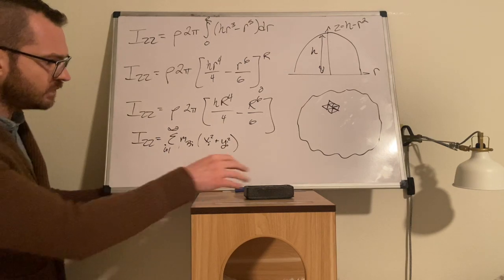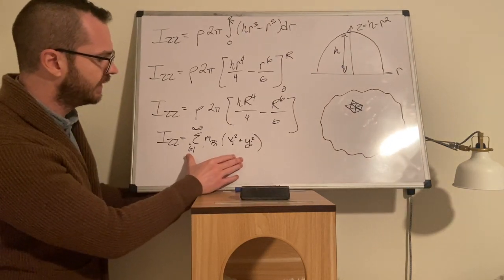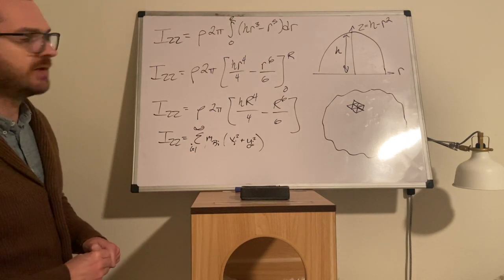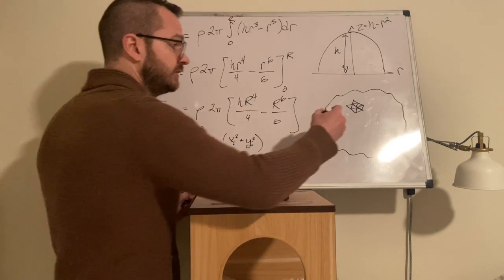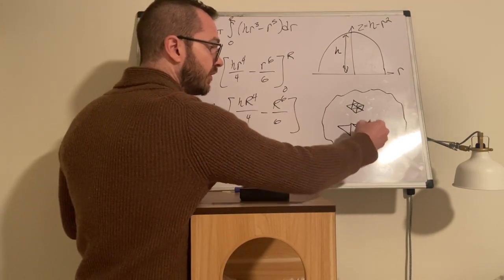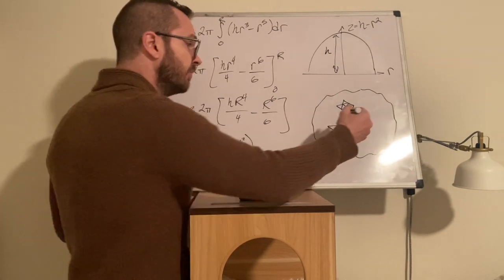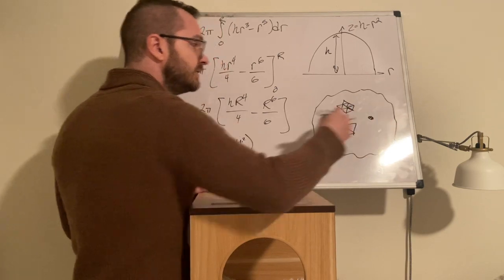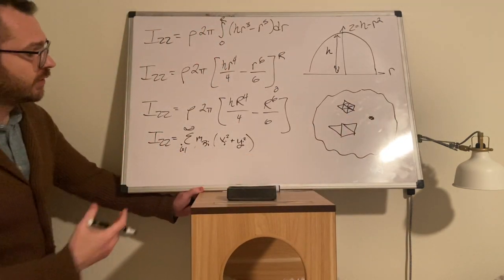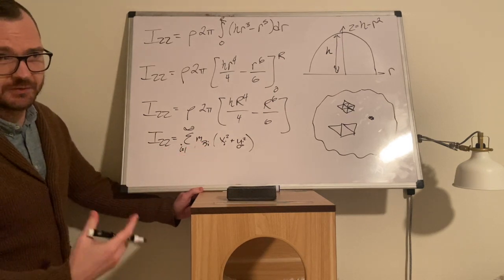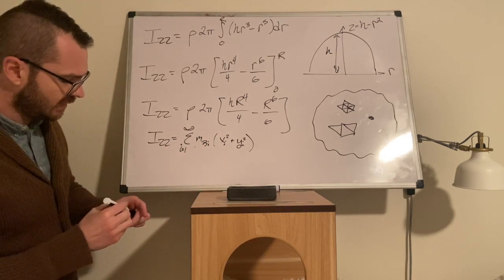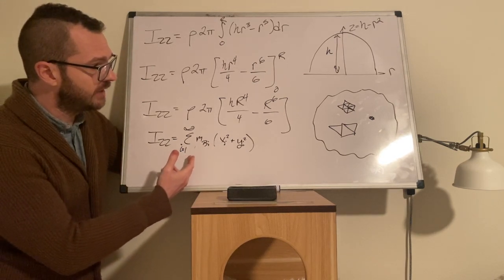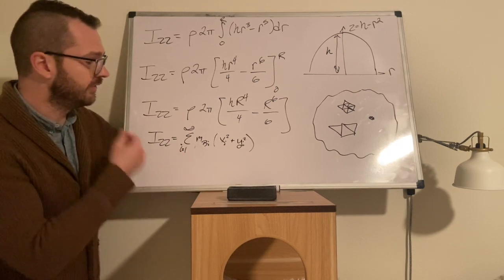Of course, how good is the answer? Well, the accuracy of the answer is really a function of how fine of a mesh you've applied. So if you apply a large mesh, then your answer is so-so. If you apply a medium mesh, it gets a little better. And if you apply a very fine mesh to this, you're going to approach, we could say, the true answer. Your answer is going to become more accurate, or you could also consider it as more precise as well, because as you approach it, you're going to get more decimal points of accuracy.